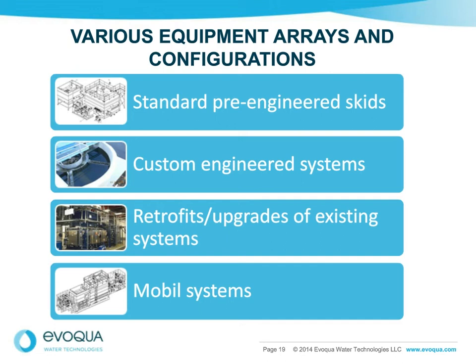For existing systems where flow rates or high solid loadings have become an issue, retrofits could be a good alternative instead of installing a new system. Hydraulic profiling and torque considerations on the drive motors and rake mechanisms must be investigated to ensure proper operation of the system. For temporary applications, trailer-mounted mobile units are available for flow rates up to 1,600 gallons per minute.